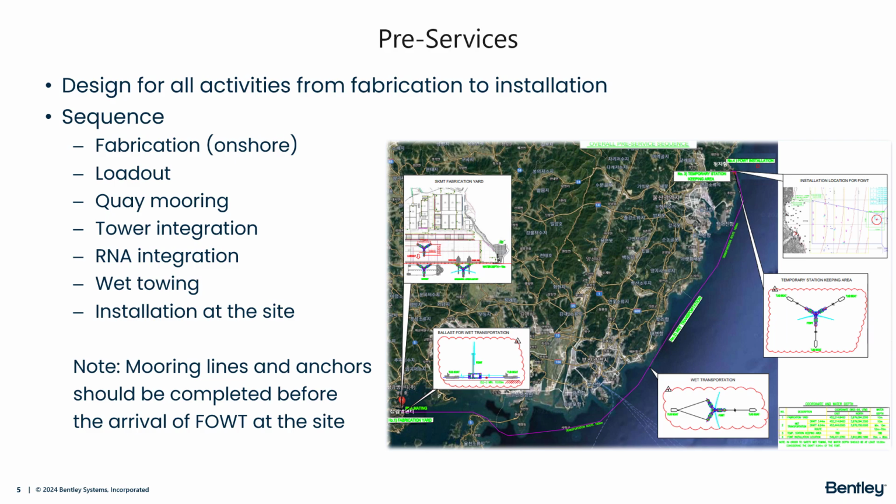At this stage, it is crucial to maintain hydrostatic stability, both with and without the tower and RNA, as well as station keeping. After assembly, the floater is towed through the sea to the installation site via this path. Ensuring structural and hydrodynamic stability during the transit is essential.